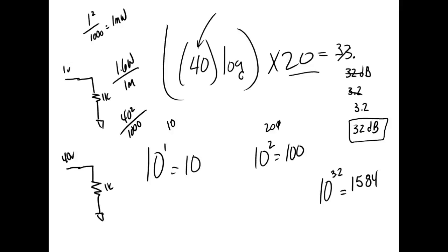But we calculated gain relative to what? Voltage. Which is pretty neat. And that's why we do the 20 log, because power varies with the square of the voltage, right? And then we used that to figure out where the 7.07 came from. Are we okay? So that help you, Dwayne?